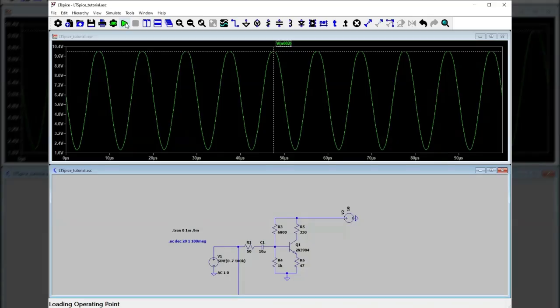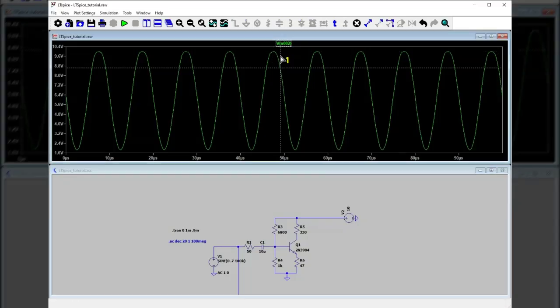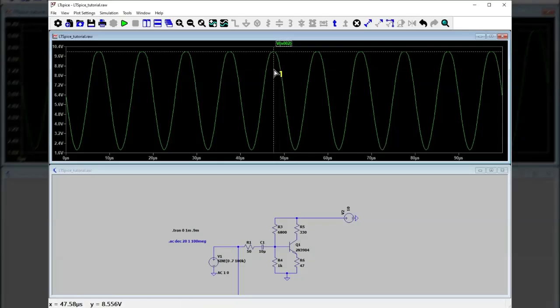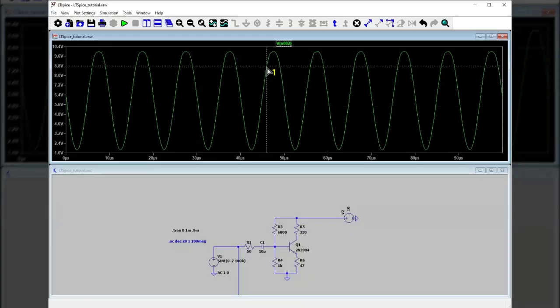And now I think you can see that we are flat topping on the top. It's not super obvious we're clipping, but if you look, the waveform is flatter on the top than it is on the bottom, and we are right at 10 volts on the peak, 9.97 volts. So we are clipping right now, but it's not grossly obvious. And if you want to see grossly obvious, let's up this to like 0.9 volts, and then we'll be clipping, obviously.